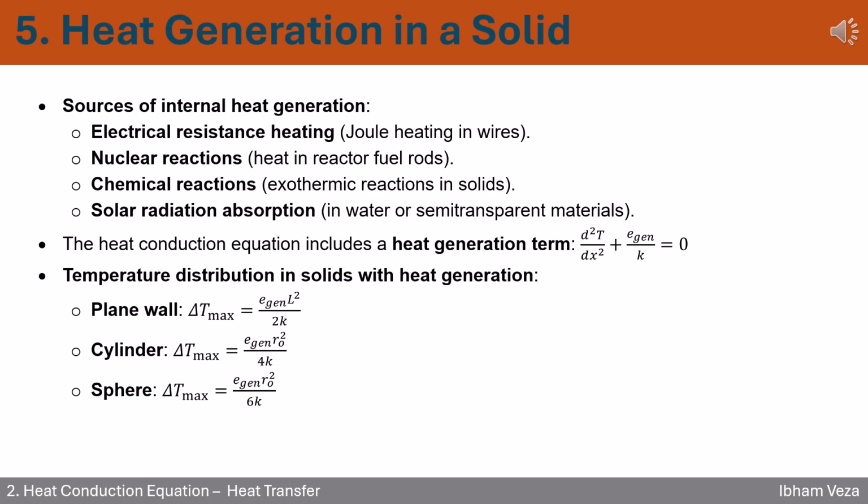5. Recognize how solids generate heat internally. Let's move beyond external boundaries and look inside the solid. Many systems generate heat internally. Think of Joule heating in wires, nuclear fuel rods, chemical reactions, or solar radiation in materials. When this happens, we introduce a heat generation term directly into the heat conduction equation.